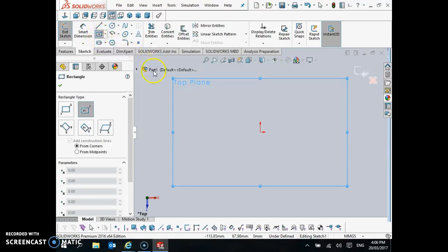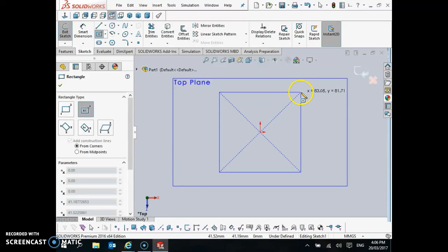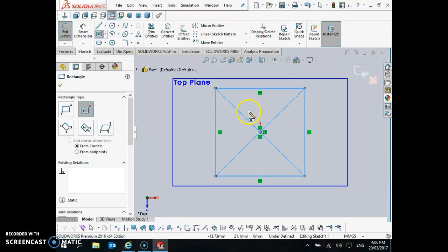Okay. So now selected, we can see rectangle selected over here in the feature tree. And I'm going to choose, type 2. Okay, so I'm going to click on the origin. So I'm just hovering over the origin, and we see the little orange dot turn up. And we can also see just below the pencil a sketch relation. I'll talk more about them again in a minute. I'm just going to click on the origin, drag it up and away, and then drop it.